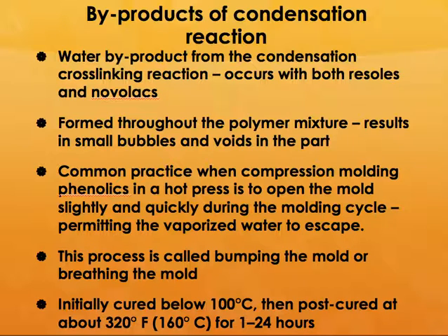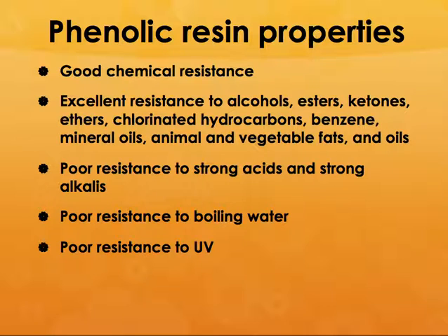And then you post cure that at about 160 degrees centigrade for between 1 to 24 hours. If it is a thicker component, then you will have to do this for a longer period of time. But if it is not a very thick component, you can do that within a couple of hours. And then usually you leave the component inside the mold itself and let it cool down inside the mold.